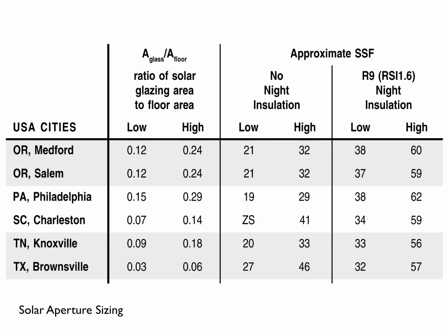Now, it doesn't double because that's a fairly low R value window and it's also losing heat at night. But look what happens when we add the night insulation or we have a super window. Then that 9%, which produces a 20% solar savings fraction, goes up to 33%. Same glazing area, we're just insulating at night or using a better R value window.